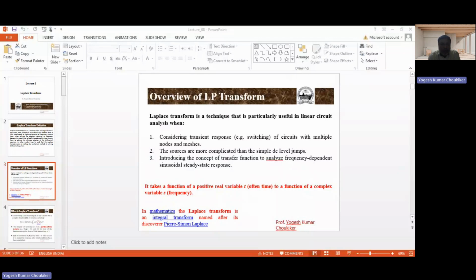Now we can easily apply the inverse Laplace transform, and that will come into the form of the Laplace property. So finally, when we take the inverse of V naught of S, it becomes V naught of t. Root 2 divided by (S plus 4) whole square plus root 2 whole square will become e to the power minus 4t sine root 2t, and this is valid for t greater than 0. Correct? This t is greater than 0.